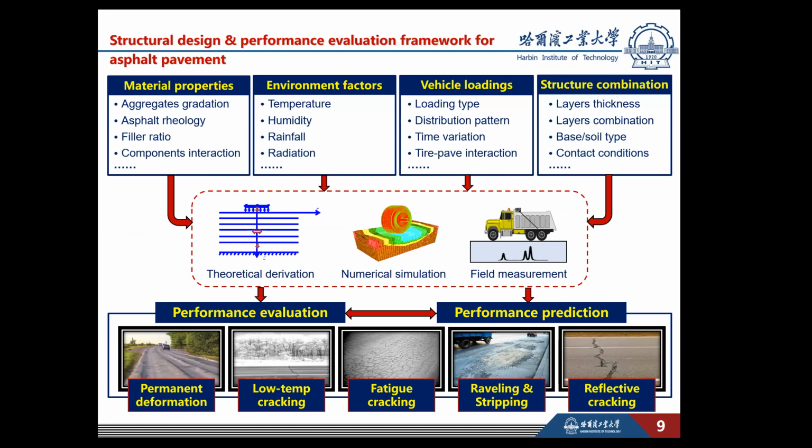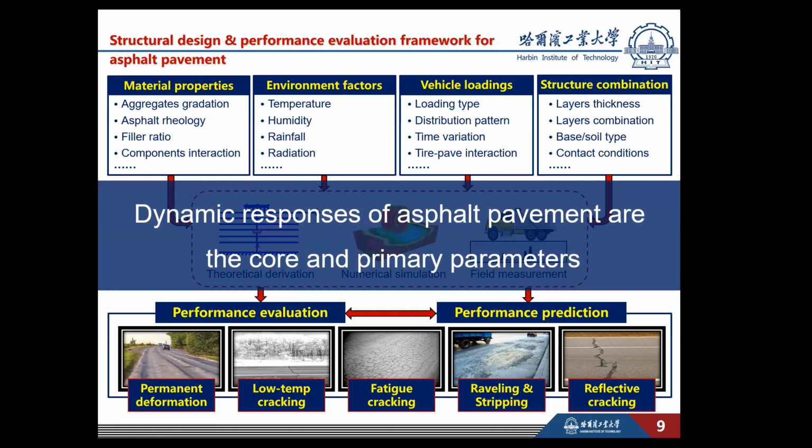Then we could evaluate or predict the performance, the service performance of asphalt pavement, like rutting, low temperature cracking, fatigue cracking, or reflective cracking. As you can see in the framework, among all these, the dynamic responses of asphalt pavement are the primary parameters we need.